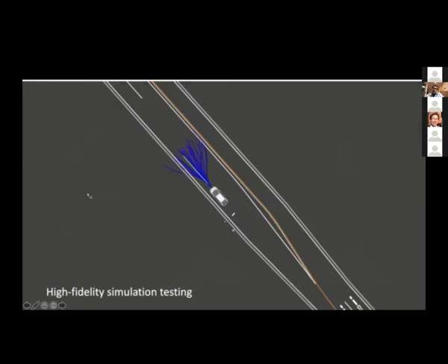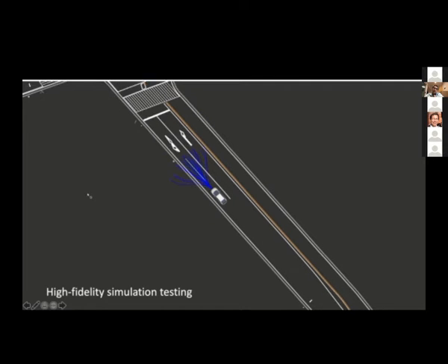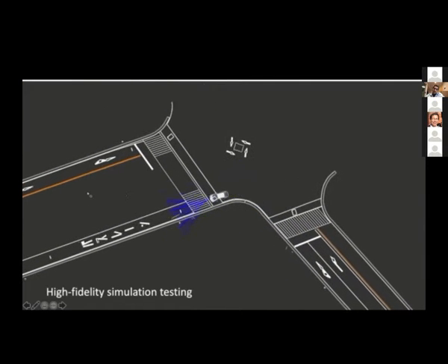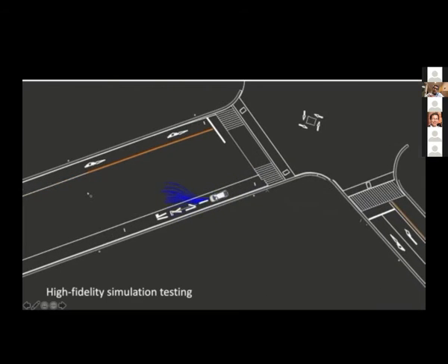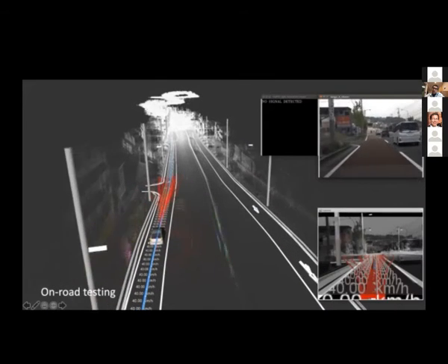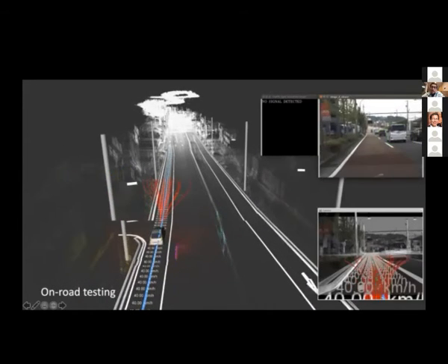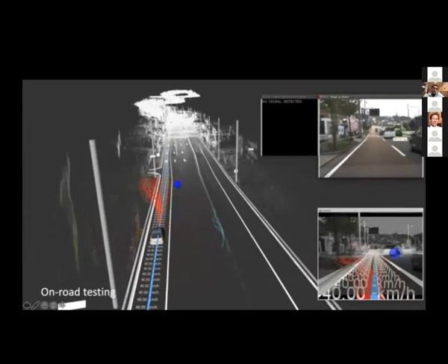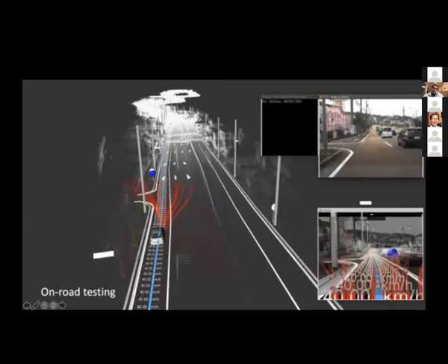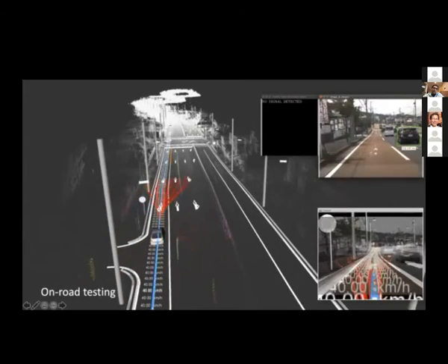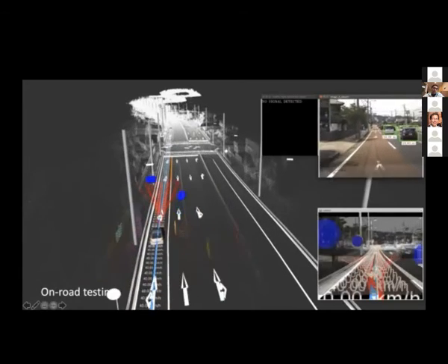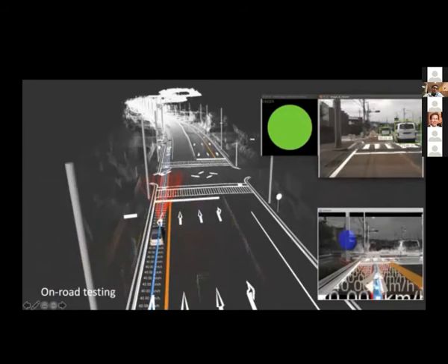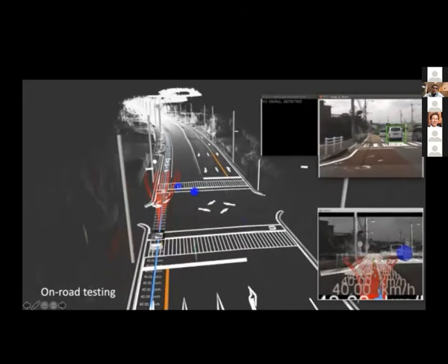And then once we were able to run it through the cycle, we went into high fidelity simulation based on the actual roads that we're going to be testing on. And then we were testing with our partners in Nagoya in Japan, where we rented out a lane. And then we started testing out these algorithms for real. It was a specific test for a local planner that is looking ahead 100 milliseconds ahead in time, and making sure that the trajectories selected are the best trajectories.